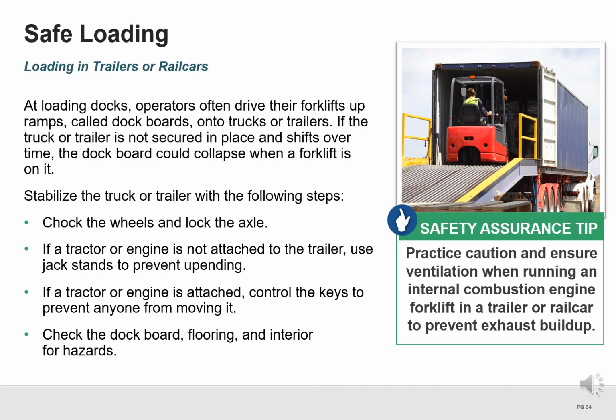Also use caution when operating internal combustion forklifts inside trailers or rail cars, and ensure proper ventilation to prevent exhaust buildup.